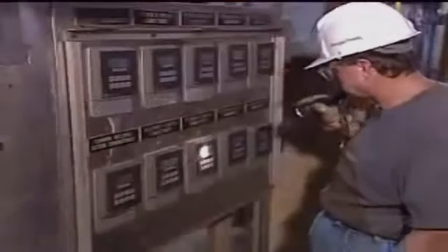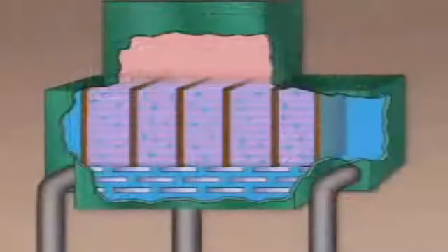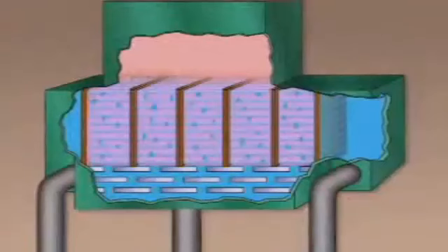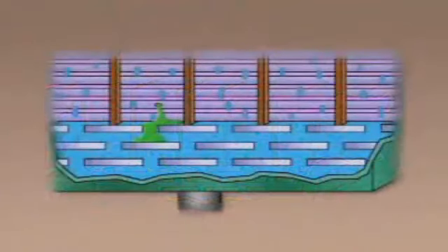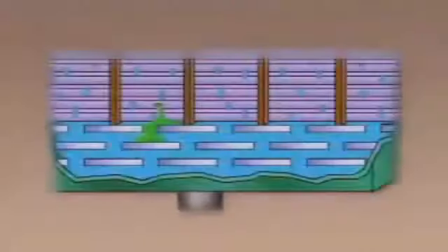Aside from abnormal levels, pressures, and temperatures, another major concern for plant operators is the possibility of condensate contamination. The primary cause of condensate contamination is a circulating water leak into the steam side of the condenser. If such a leak occurs, circulating water, which is impure, will mix with the pure condensate in the shell. Condensate contamination can be detected because the mixing of the two liquids will affect the electrical conductivity of the condensate.